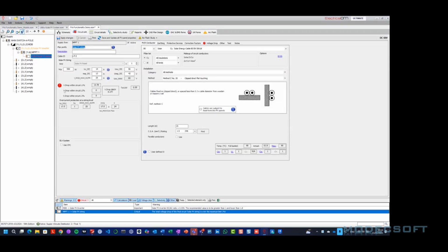And as you can see, again, using the manufacturer's data sheets I showed you earlier on, we're going to define the characteristics of our module. So our PV modules will be 500 watts. The short circuit current at standard test conditions will be 14.17 amps. In addition, we've been defining the maximum power current of our PV modules at 13.59 amps.